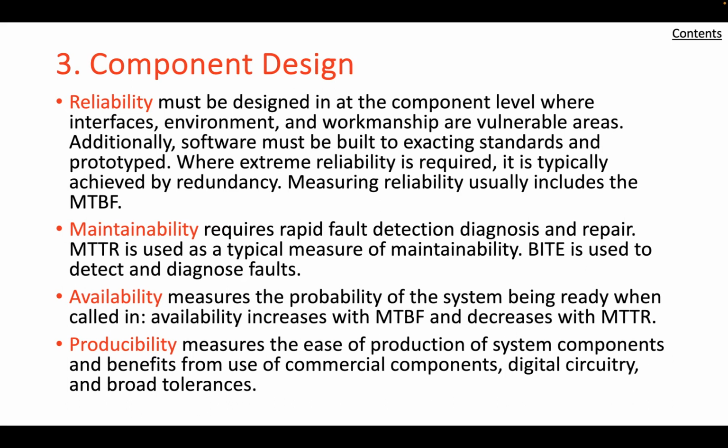Component mounting. Systems subject to shock or vibration during operation or transport must have suitable shock mountings for fragile components. Temperature and pressure. Systems subject to extremes of temperature and pressure must provide protective controls at either the system or component level. Contamination. Components susceptible to dust and other contaminants must be assembled under clean room conditions and sealed if necessary. High voltage components. Components using high voltage, such as power supplies, require special provision to avoid short circuits or